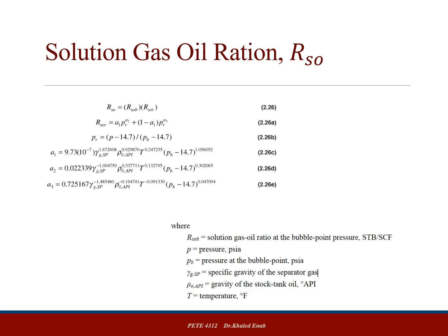So this correlation is included in the book, and as you can see, the function of it is to predict the gas oil ratio. If you go through the equations, you can apply them straightforwardly using any coding language or Excel or whichever you feel comfortable with. So we use, as you can see here, the bubble point. And how would you predict the bubble point?